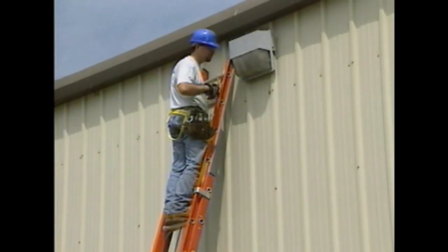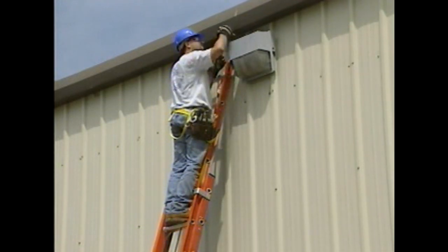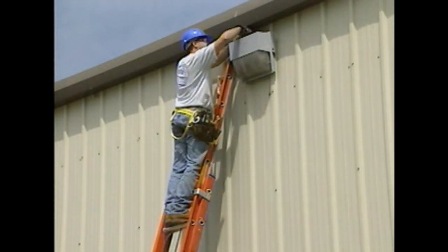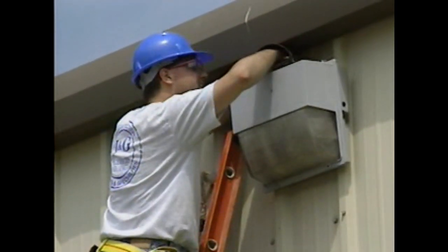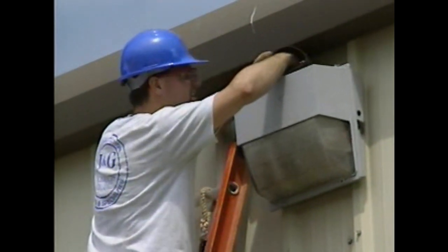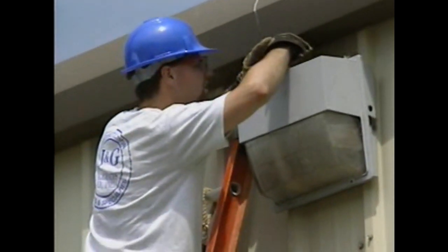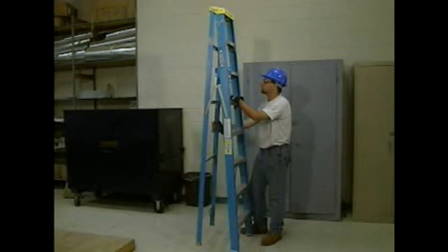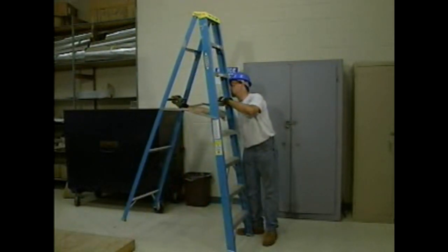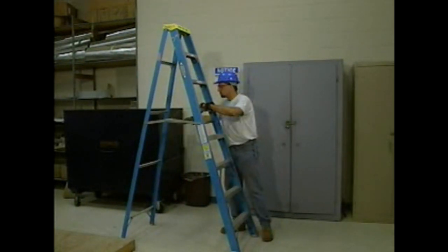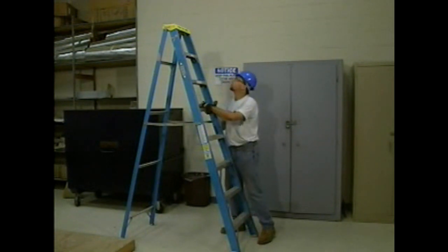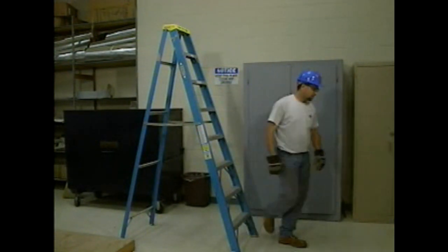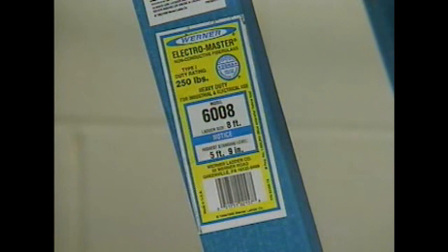Ladders are commonly used to enable personnel to work in elevated locations. But anytime work is performed above ground level, there's an increased risk of an accident. To reduce the chance of an accident associated with using a ladder, some basic safety guidelines should be followed. In this part of the program, we'll identify some of the basic safety considerations that apply to straight ladders, extension ladders, and step ladders. We'll also look at how to select and use the proper type of ladder for a job.